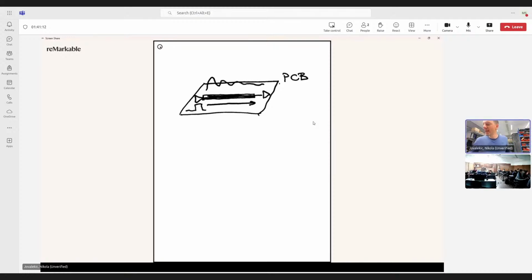What can happen if this attenuation is big enough? Then this digital receiver here will not be able to decode this pulse, and we will have so-called bit error rate, bit errors. So that's why we want to have a dielectric below which has small tangent delta, and this is something which you are going to ask the PCB manufacturer to give you, some material options, and then you will take that for the simulation to see what's going on there.